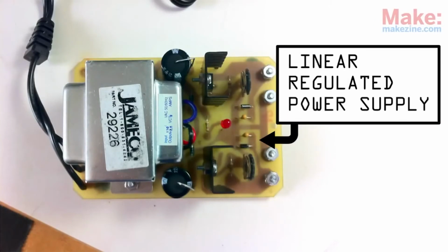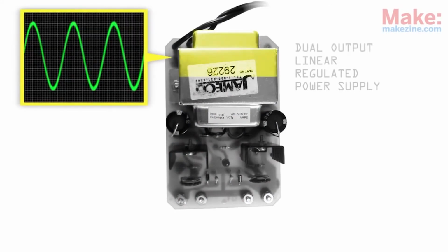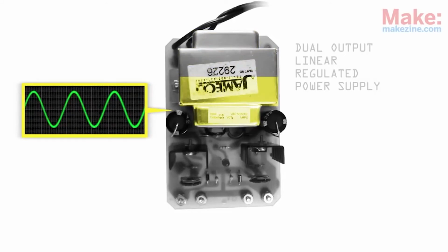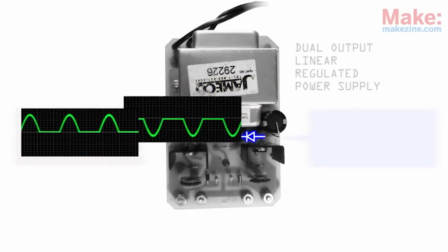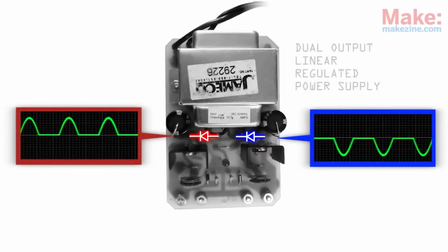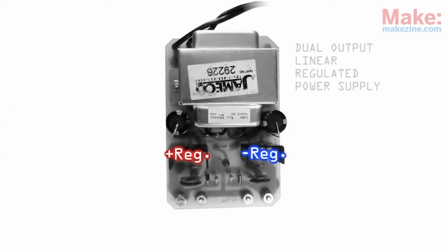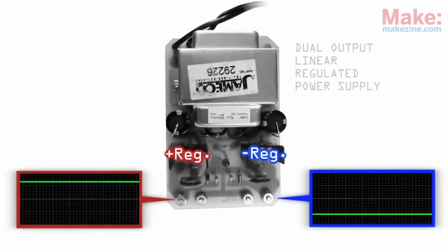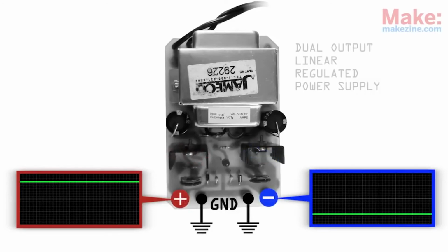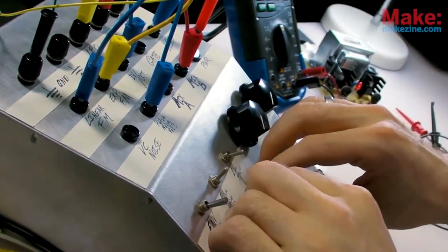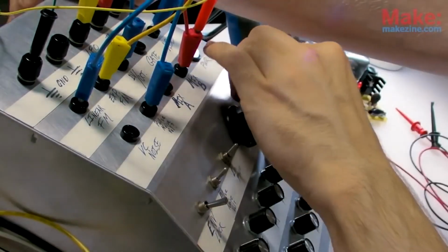A power supply can be external, often seen in devices such as laptop and phone chargers, or internal, such as in larger devices like desktop computers. A power supply can either be regulated or unregulated. In a regulated power supply, changes in the input voltage do not affect the output. On the other hand, in an unregulated power supply, the output depends on any change in the input. The one thing all power supplies have in common is that they take electric power from the source at the input, transform it in some way, and deliver it to the load at the output.